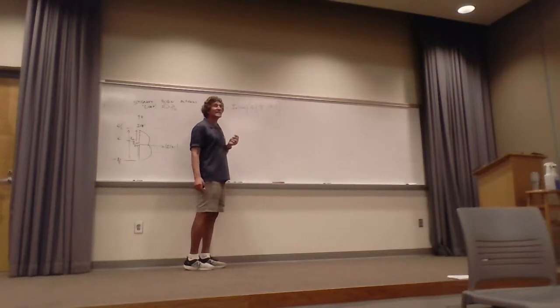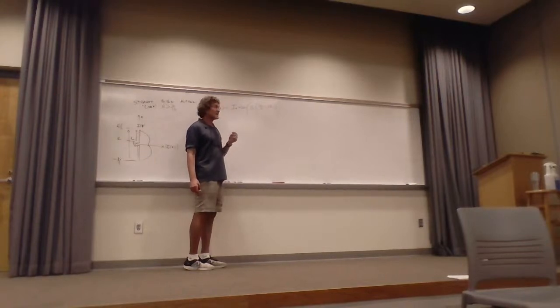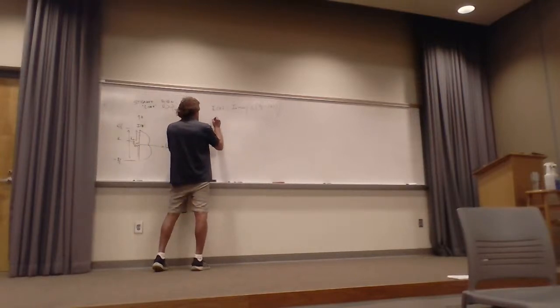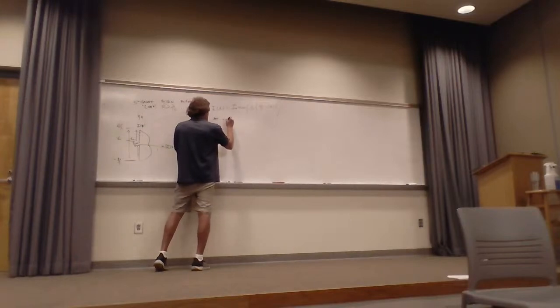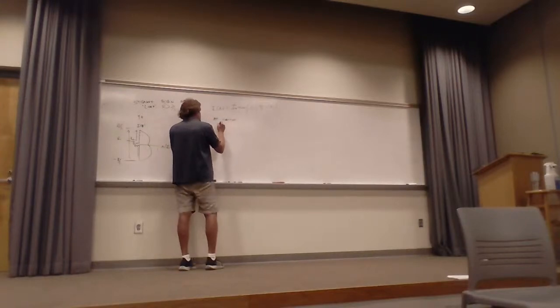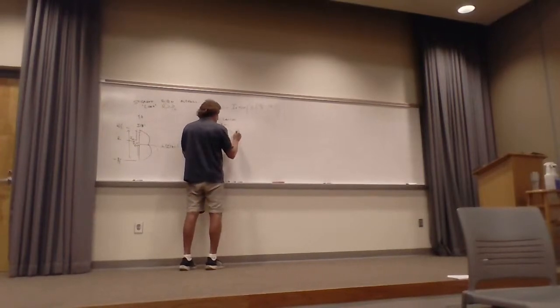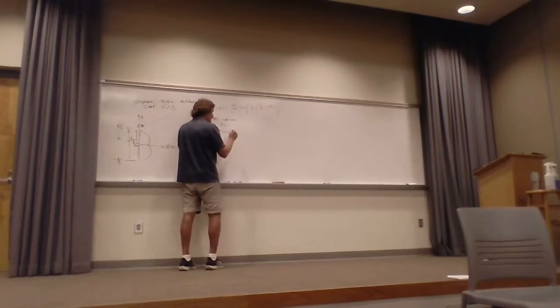All right, so what is it at the center? Well, at the center, it's the sine of beta L over 2, right? Now hear me. That does not have to be 1. Y'all follow me on that? Think about it now. At the center, and you can write this down, that's Z equals 0, I of Z equals I naught.